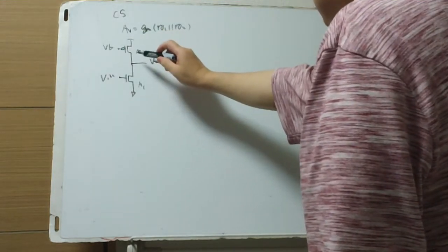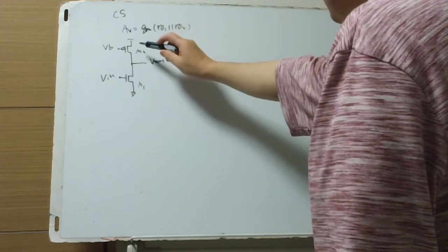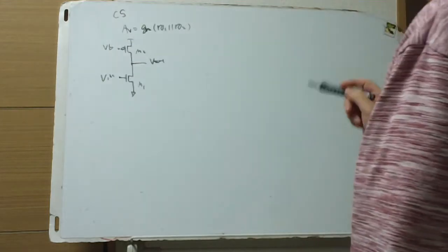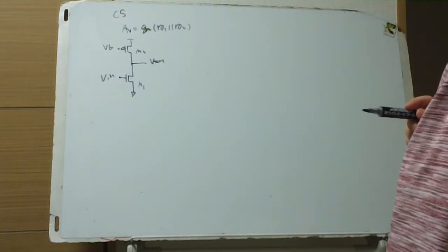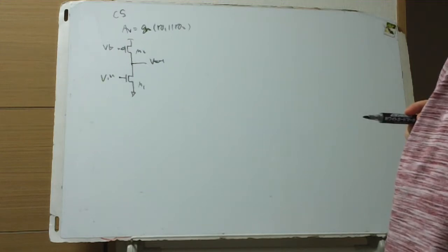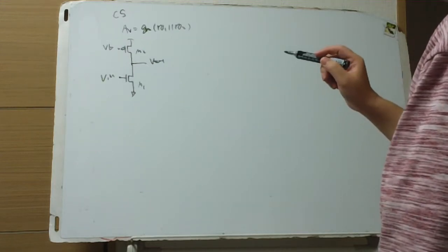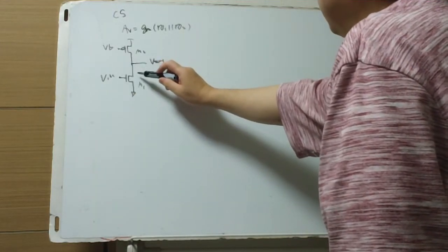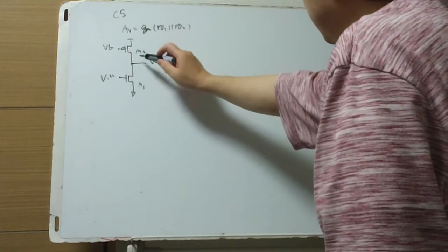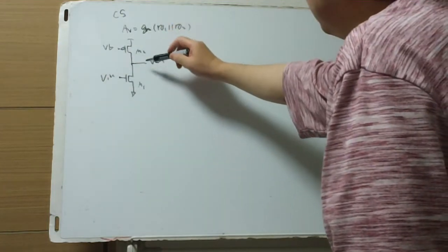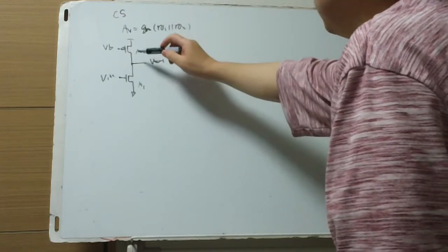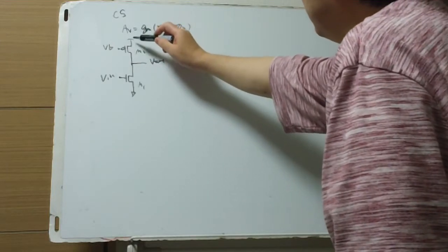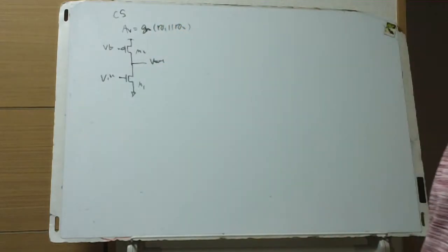And R01 is the source-drain on-resistance, the differential or derivative resistance, and the same for R02, and they are in parallel combination, looking from Vout to AC ground, VDD and ground.